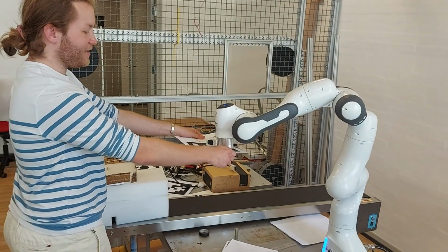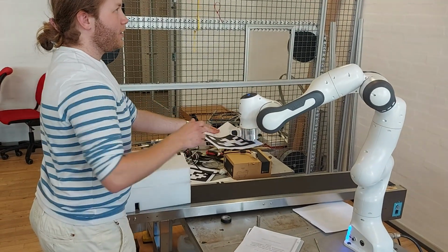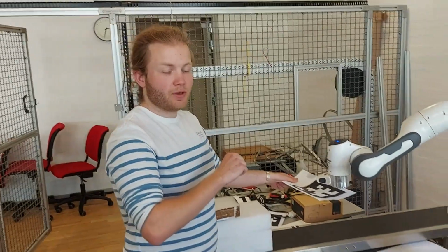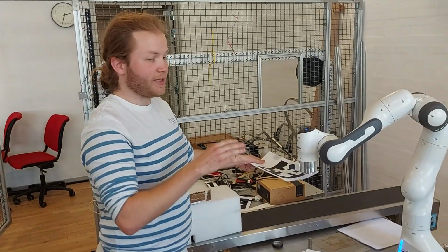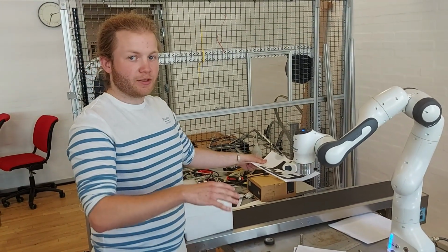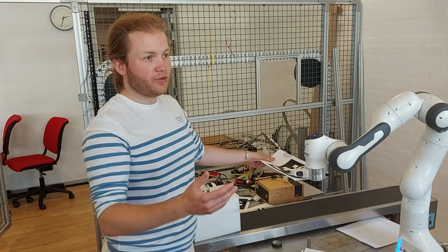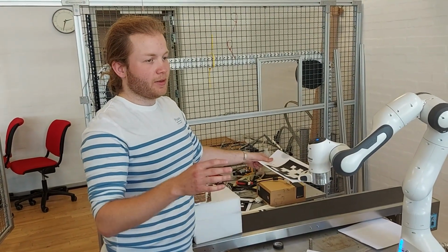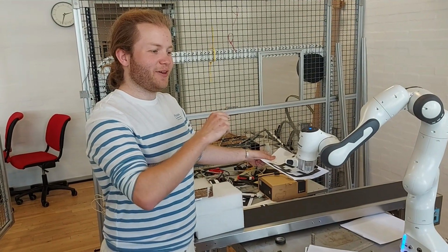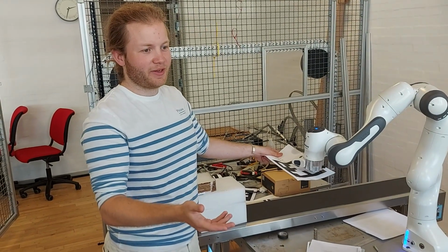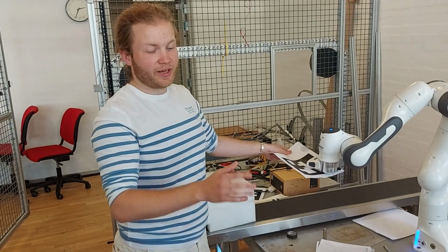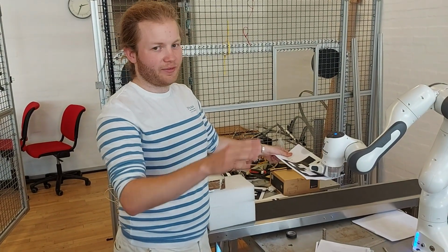That's basically how it works. Initially, I was using just the predicted position, and I'm still just using that in task space. But because the inverse kinematics solver only does inverse kinematics, it doesn't do inverse dynamics, I'm not using the predicted velocities for anything right now. But from the joint space positions that are generated by the inverse kinematics, I use those to generate velocity references,